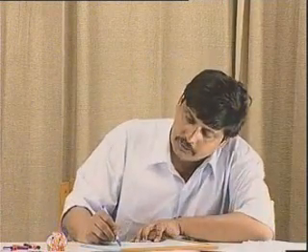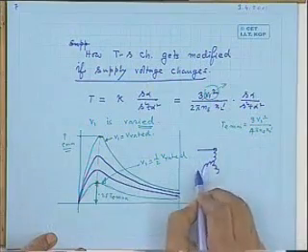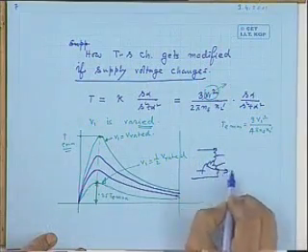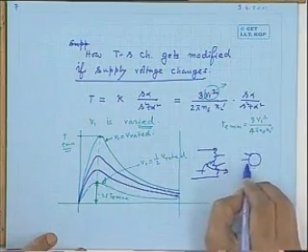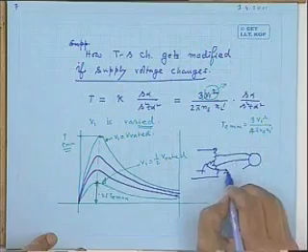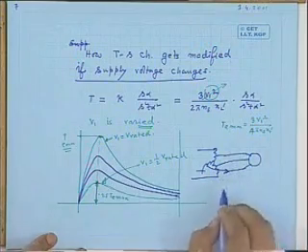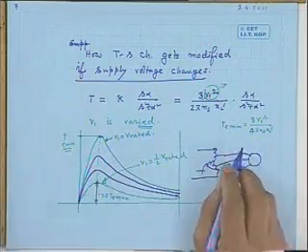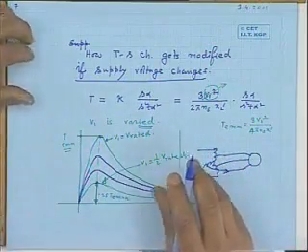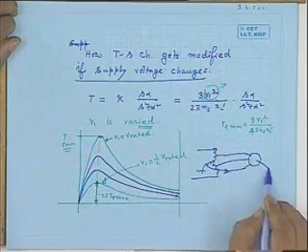All of you have done some basic experiment on induction motor. Tell me, how did you start that induction motor? While starting, did you apply full voltage? You applied from 0 voltage with the help of a variac and went up to the rated voltage. Is it not? Just listen to what I am trying to tell. Suppose this is your variac voltage, and this is your induction motor stator, with 3 terminals coming out. You give supply. Suppose from 0 voltage you are increasing the value.